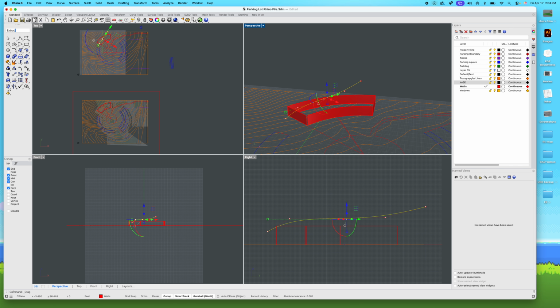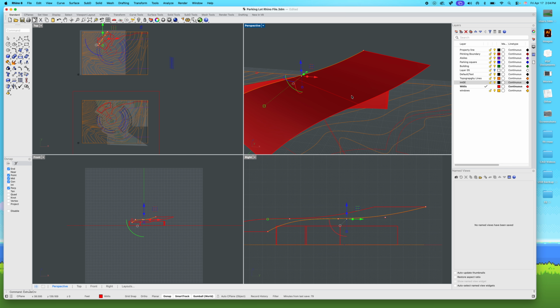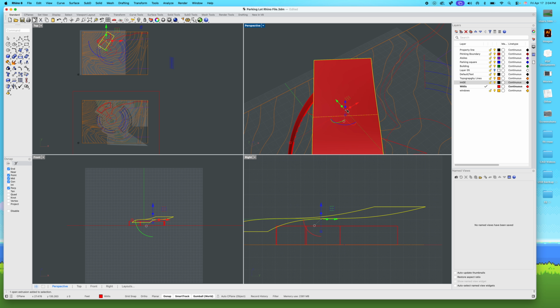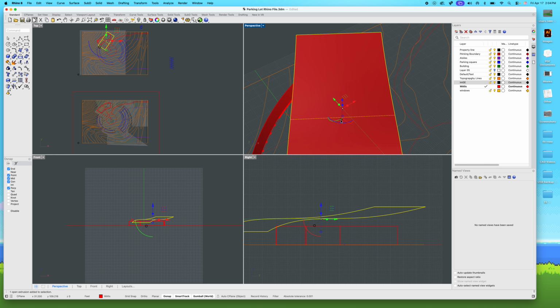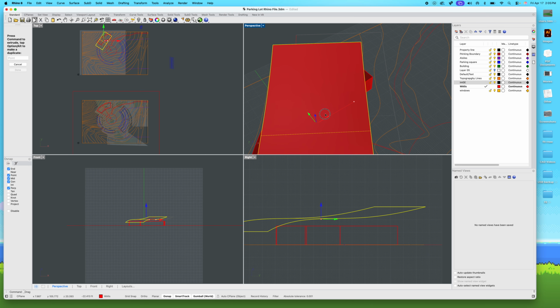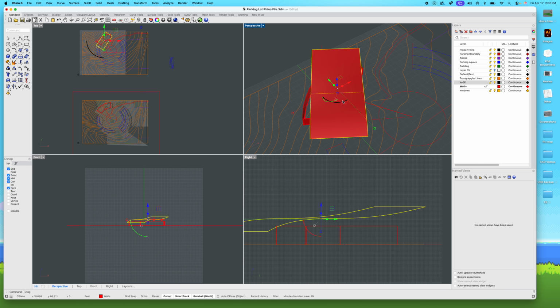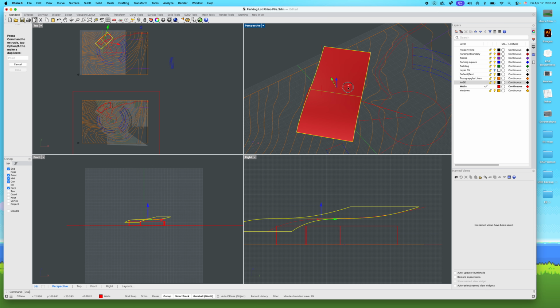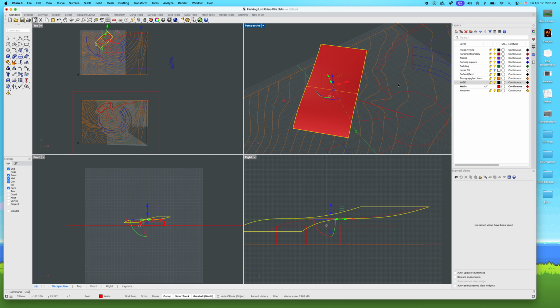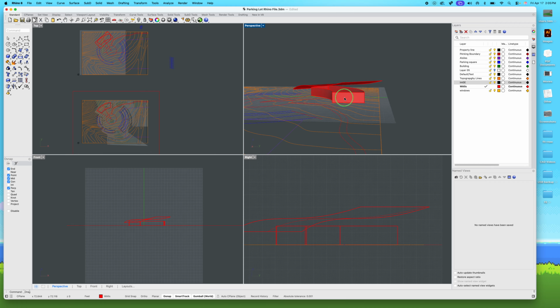We can extrude it, just like any other curve. We can go, okay, well, I want it to be about this big. And if that's looking weird for you, you can always reset this by hitting that impossibly hard white little circle. And you just say reset Gumball. So auto reset or just reset the Gumball, right? So again, super useful in many cases. I don't even think I show my computer graphics sometimes, that thing. But that's actually looking a little better.